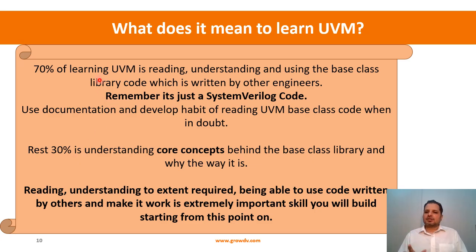So 70% of it is that you will understand these are the different base classes, these are the various methods, which of them are virtual, which are non-virtual, how you call them, and what functionality you are supposed to implement in each of those virtual functions. This is the 70% of UVM. It's understanding some SystemVerilog code that has been written by others. And the 30% of it is some core concepts, right?